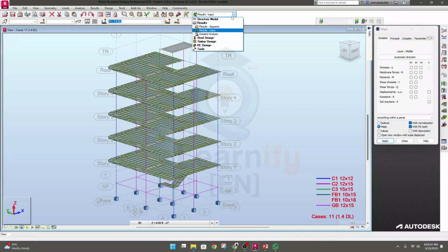To complete the design, I have to go here, RCC design. So I'll click here for RCC design, and in RCC design we have many options. So what do you want to design? Slab provided reinforcement, slab punching. As we have no slab over the column, no punching will be available. Slab reinforcement, I only need right now the RCC member. Okay, RCC member. So what will be the RCC member? Beam and column actually.